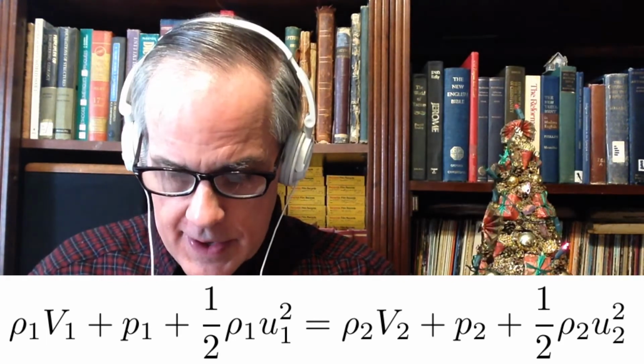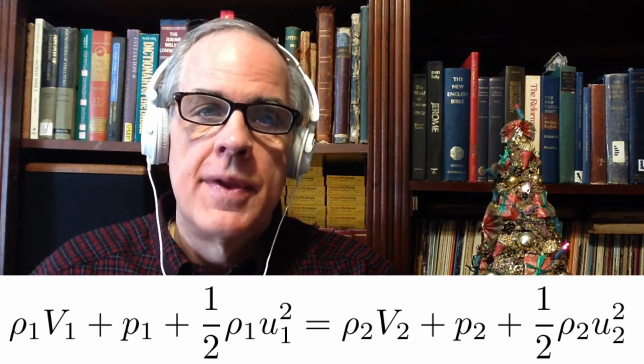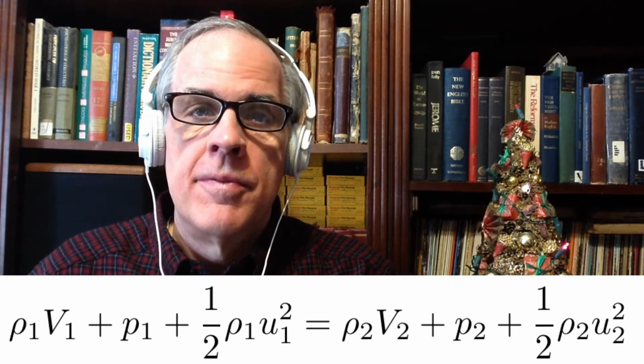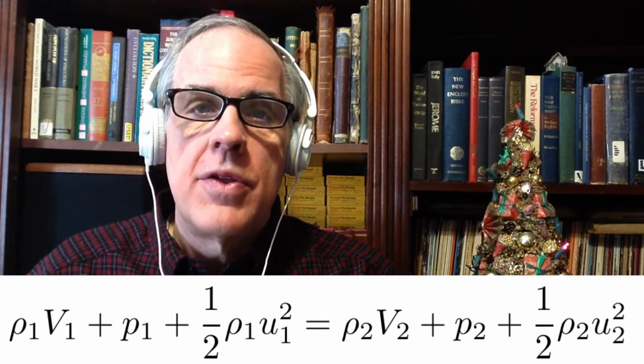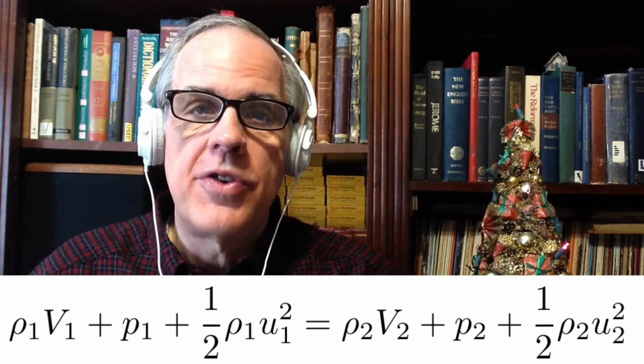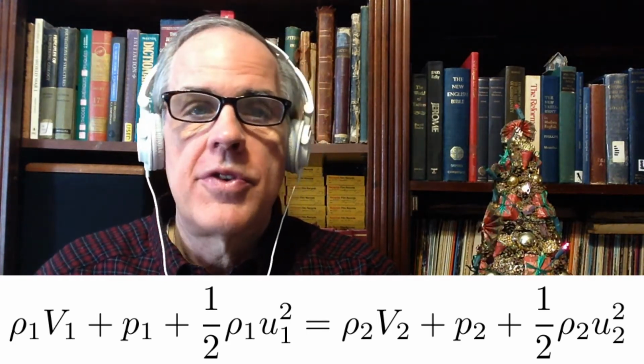And so the last one is velocity or kinetic energy, the fluid in motion. And so with those three, we basically say that the sum of those energies at state 1 is equal to the sum of the energy at state 2. And with that, we're also going to assume, since it's incompressible, that the two densities are the same. And with that out of the way, we do a little math and we end up with an equation that basically has only pressure and kinetic energy.